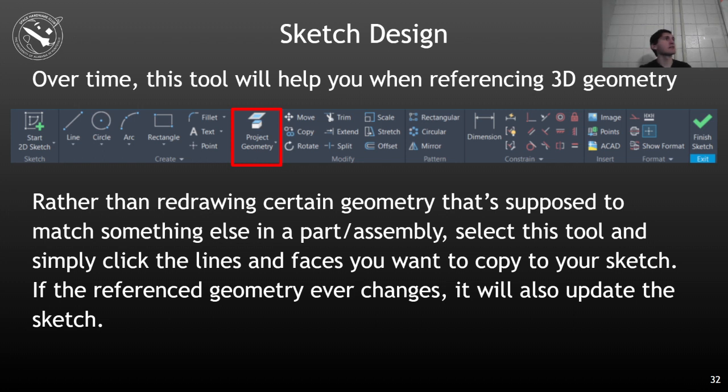If you make a sketch that has the positions of all those holes, to make the second feature, you can just reference the circle that's being made, and then add some dimension from that referenced circle. Say you want to change the circle to 10 inches diameter. If you didn't reference it at all, that second feature will keep all those holes in the same position. It's going to have a cluster of holes in the middle, but not near the edge where you want it. If you use the reference tool or the project geometry tool, the circle is modified as you change that one feature, so all the holes will also move with it to the outer part as you change the size.